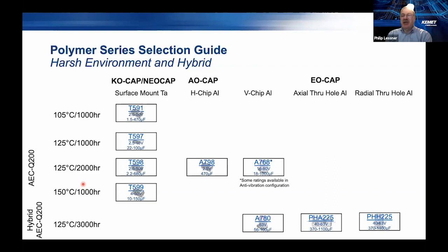By wet electrolytes, if you mean wet tantalum type of capacitors, then our polymer Hermetic seals are just as reliable as the hermetically sealed wet tantalums, and they have advantages of better cap stability with temperature and certainly better ESR. So it really depends on the particular wet electrolytic system that you're looking at.